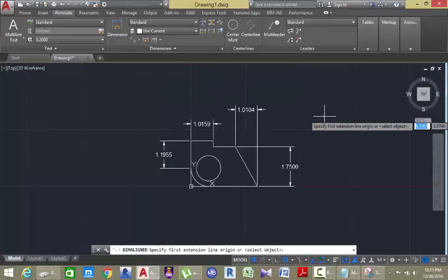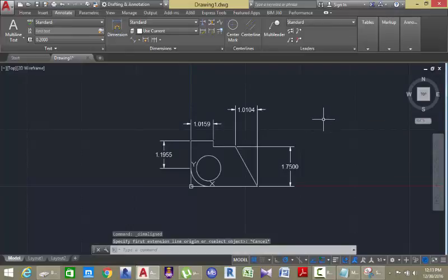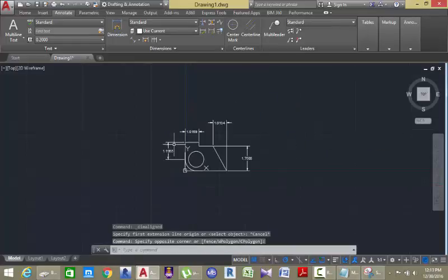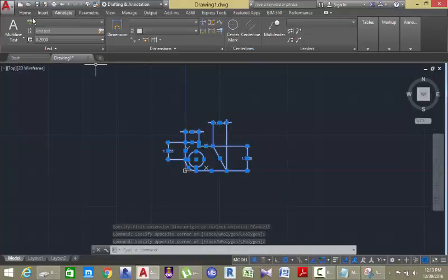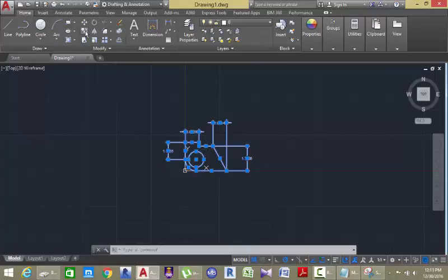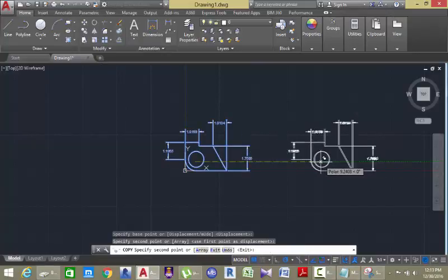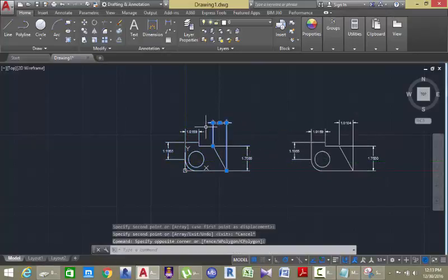With the align dimension, for now, let me erase the dimension that I have in the drawing. Well, let me copy this to a new area so that you can use the measurements in this one as a reference. Go to the Home tab, Modify panel, and select the copy command. Copy this drawing into a new location, escape, then erase all the dimension in the original drawing.